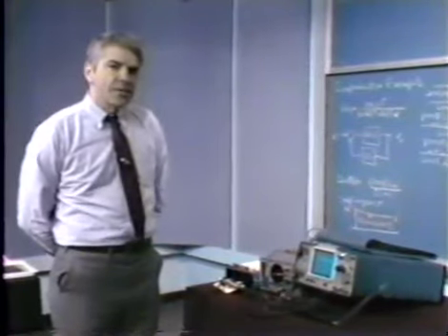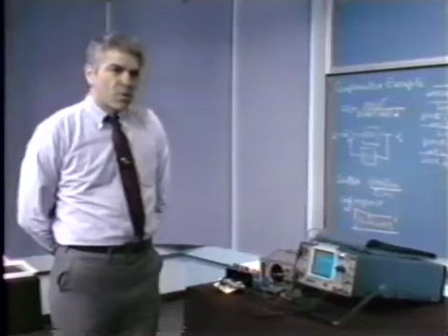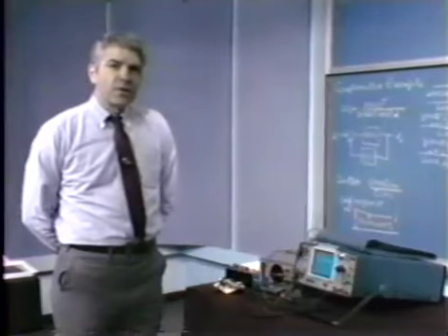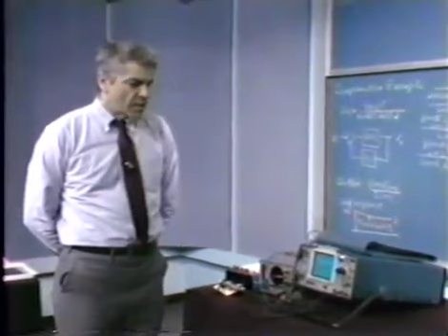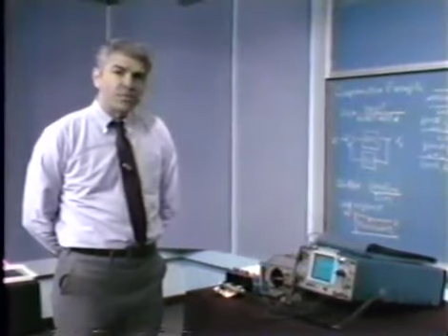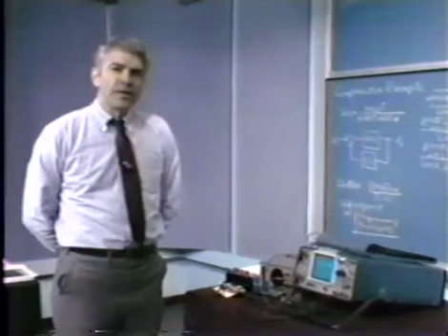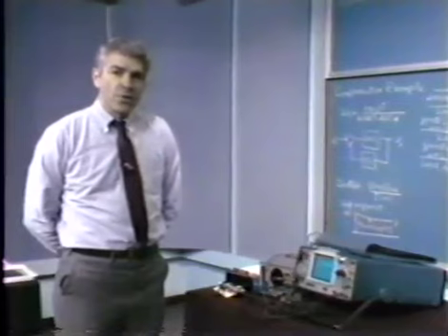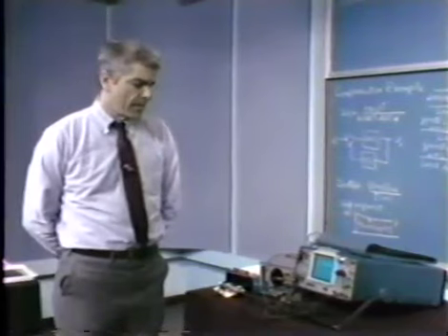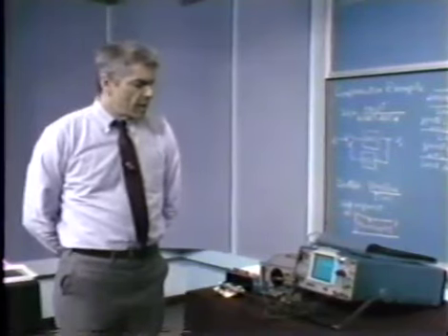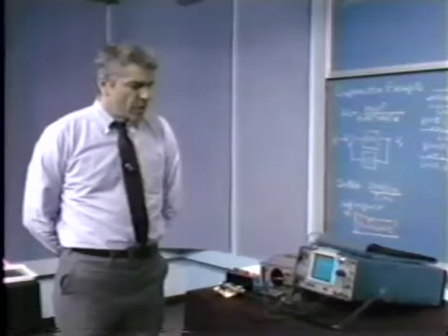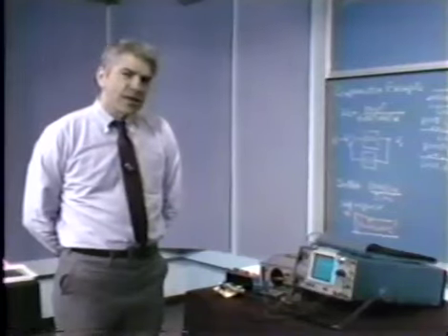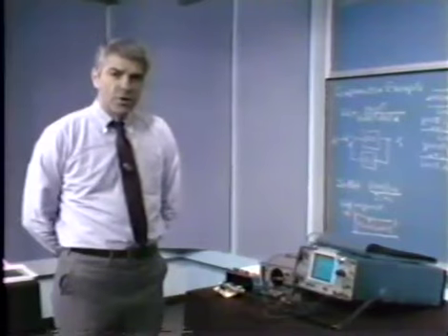But let's think a little bit about the effect of crossover frequency on the oscillation associated with the step response. We said that from the Bode plot, we find that this system crosses over at about 2.4 times 10 to the 4th radians per second. If we divide that number by 2 pi, we get something like 4 kilohertz for the crossover frequency of